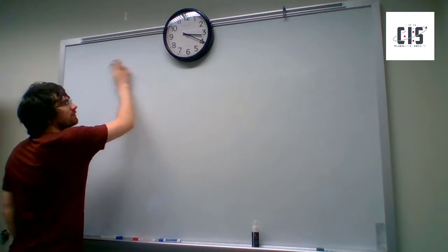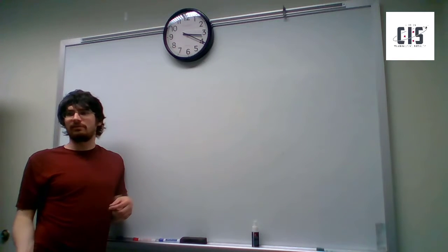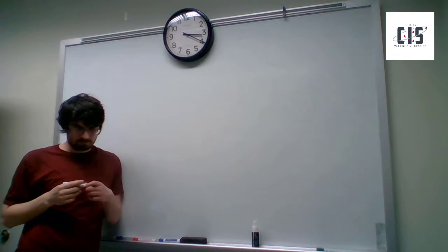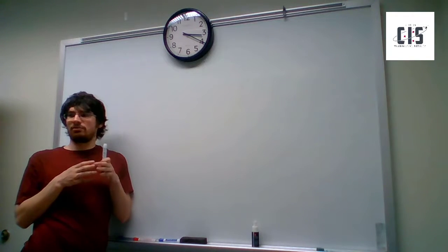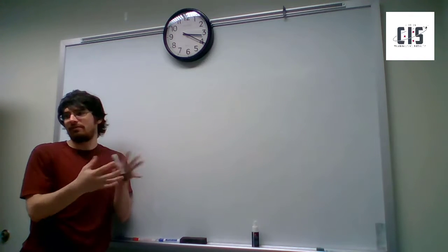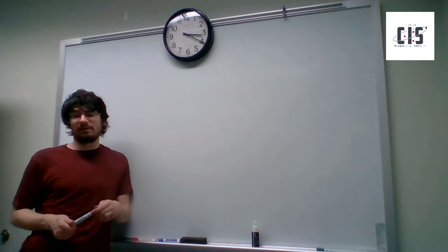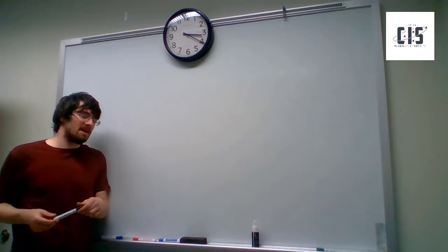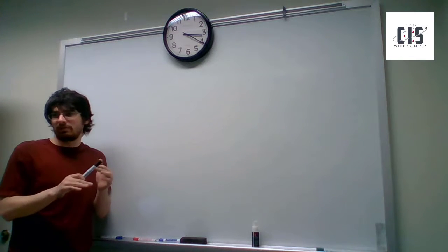So, are there any other questions on that briefly? If it was a sphere, what would the curve look like? Exactly the same. I haven't given you a formula for this. Actually, the line I drew assumes that the whole thing is at constant temperature. As soon as a little bit of energy touches the surface, the entire thing changes its temperature immediately. It's one of the simplifications that is common in thermo. But in reality, having a larger surface area means heat transfers more quickly.